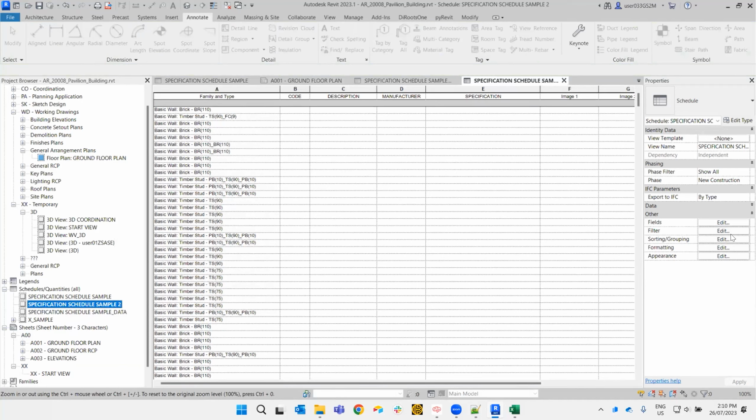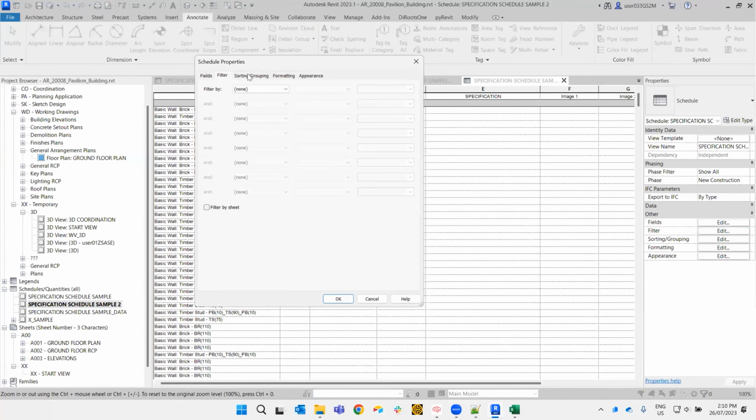My personal favorite for filtering these down is to filter them so that the, say, keynote or tag or category tag mark value, type mark value, actually has something in it. So I'll usually go keynote is greater than nothing. So basically, if it has something, it will schedule. So that will help us here.